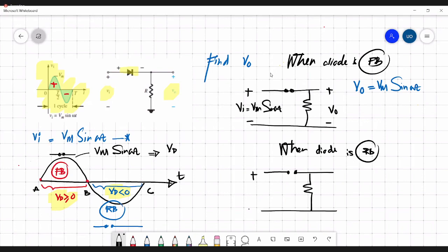So here you have input voltage Vi. So this is your output. So for this, what about V out? V out is simply 0 because it's open, and this source voltage is simply isolated from the resistor. Due to this discontinuity here, you can't apply whatever the Vi across the resistor. So the output voltage, or the induced voltage across the resistor, is 0. If the diode is forward, this is the output voltage. If it is reverse, this is the input voltage.